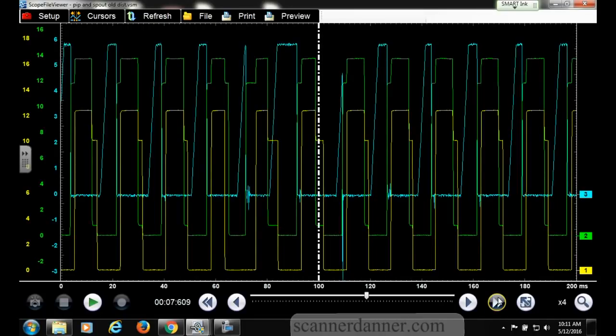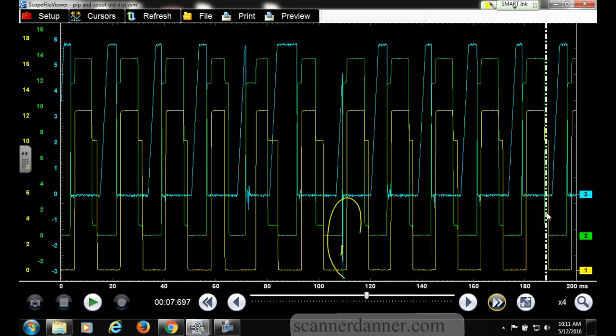It seems to always be after that one. It does, doesn't it? After. Look at the spark line off of it too. You talking about this blue trace right here? Yeah. Now think about that. That's when spark occurs on all of these. So it's the tail end of the coil current ramp. The blue trace is where spark occurs. And I don't know that necessarily tells us anything, because we would have one of those in every single one of these. We just happen to pick it up in this particular one.